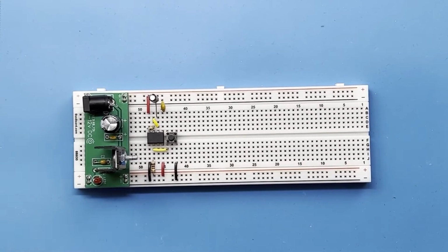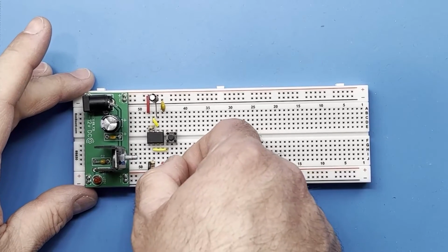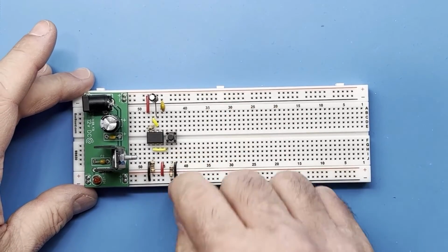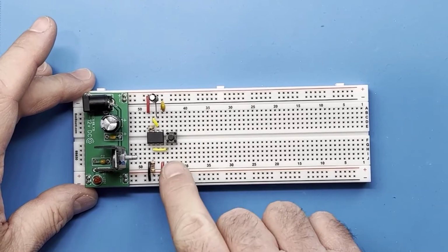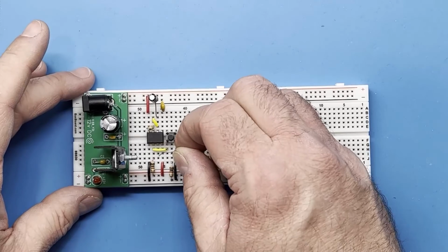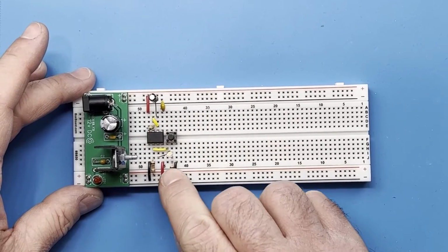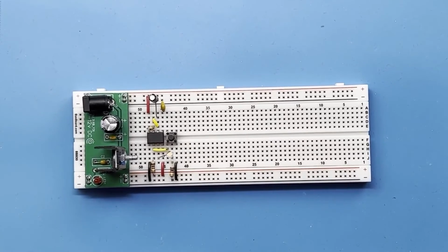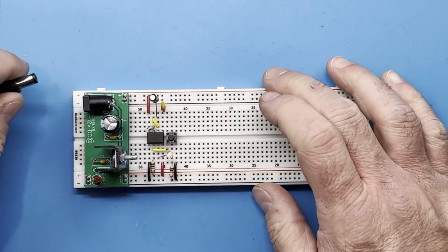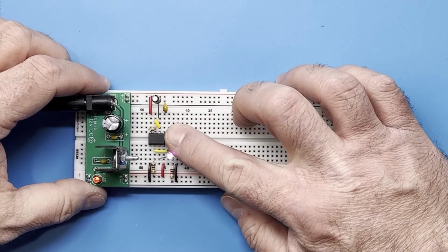So let's also hook up an LED through a 1K current limiting resistor to ground. This will give us a visual indication of the clock value. I'm setting it up there in between the two pins of the push button, but it's not connected to it, just right there in the middle. And so with that, let's test it and see if we get blinky lights. Sure enough, there it is.